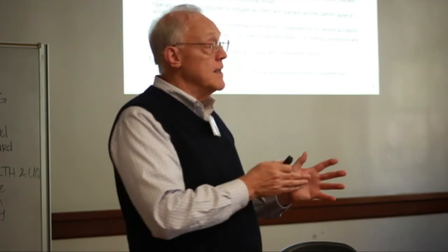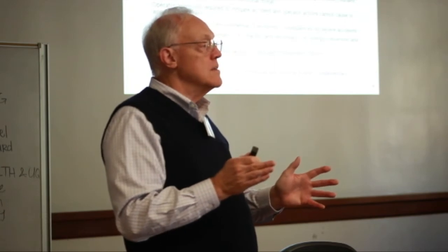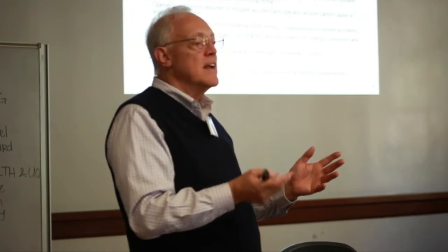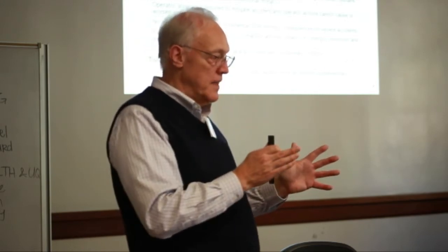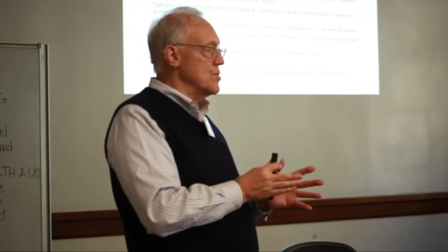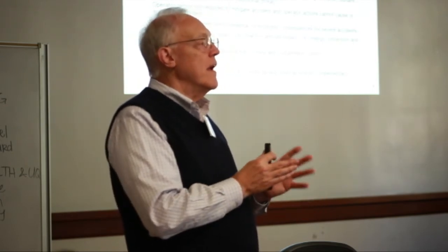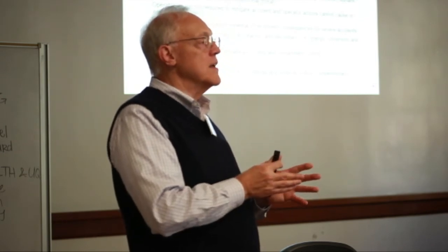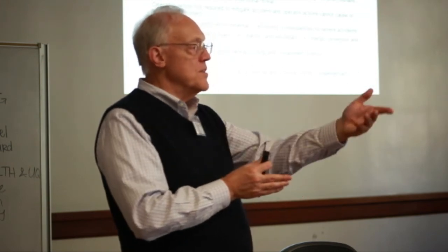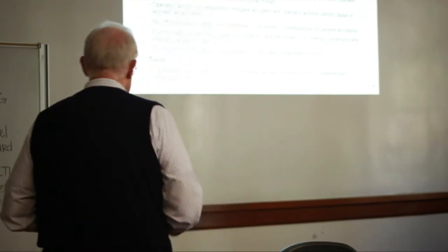Okay, and they want that to be zero, obviously, but they want no threat in reality. The light water reactor, whereas it can fulfill all the requirements in regards to how we typically license reactors and the protective action guidelines, et cetera, loses in that conversation because of the accident source term and the potential release that occurs. And hence it challenges their investment. So they would never think of putting a water reactor next to their plant for that reason. So there are other considerations I just wanted to put on the table here that have to do with why you might drive yourself down this kind of path.